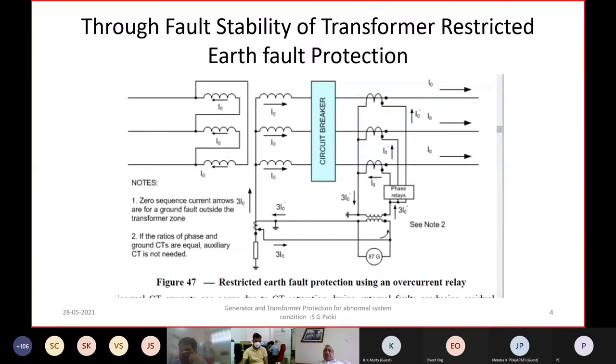of the fault current. So normally you calculate the voltage on the secondary circuit, including the cable lead resistance and CT resistance, and see how much is the maximum drop which will come across the relay. But at the same time, you also have to give at least a safety factor of 2 in the setting, so that it doesn't result in operation for the through fault condition when the voltage developed reaches the pickup value.